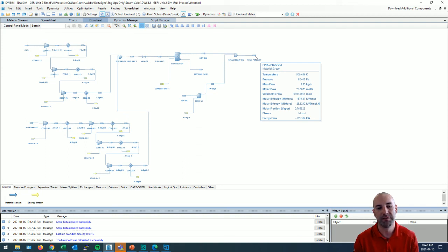This means that 77% of the water that you've inputted into this system is now steam, and the other 23% is liquid. If you wanted to run a higher salt content in your water stream, or if you just wanted to do hot water heating, we can definitely do that. We just would ramp up the water rates much higher. We've operated our system at as high as about 87% steam quality.